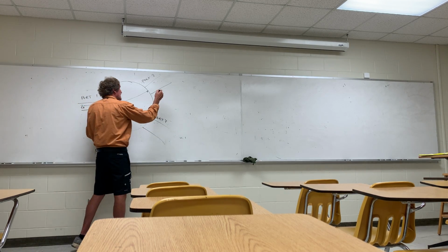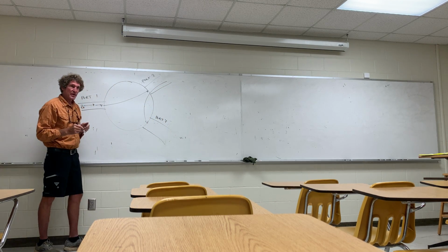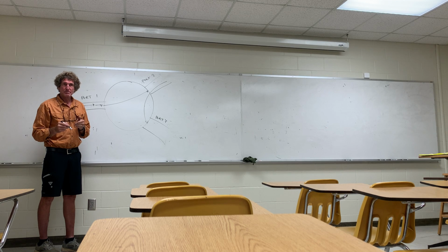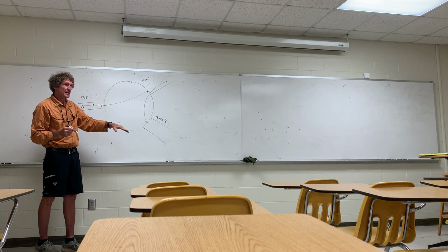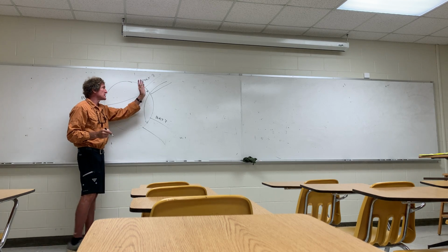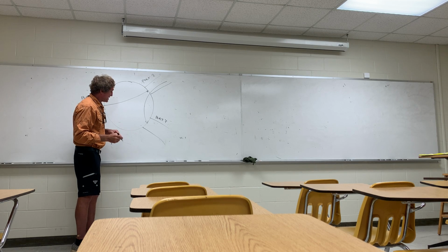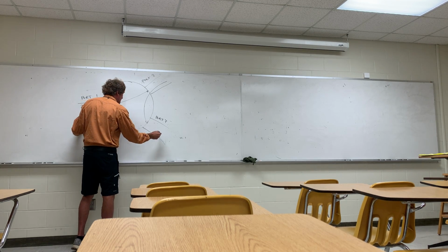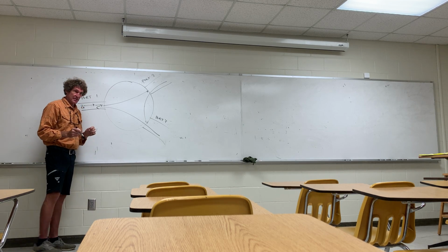By the same token, anything that comes in port 2, I want to come out port 3. Anything into port 2 comes out port 3. And the reflection coefficient at port 2 is going to be 0. So nothing's reflected, ideally. And then everything into port 3 comes out port 1. That's the idea. Y'all follow me on this?